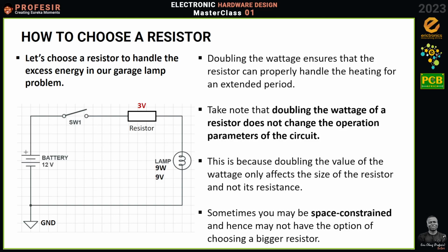So I advise that when you are dealing with resistors, always try to calculate resistance from voltage, from Ohm's law, instead of from the power relation, right? Unless you accurately know that the wattage you have been given is exactly as intended and not bloated, like as I do. All right.